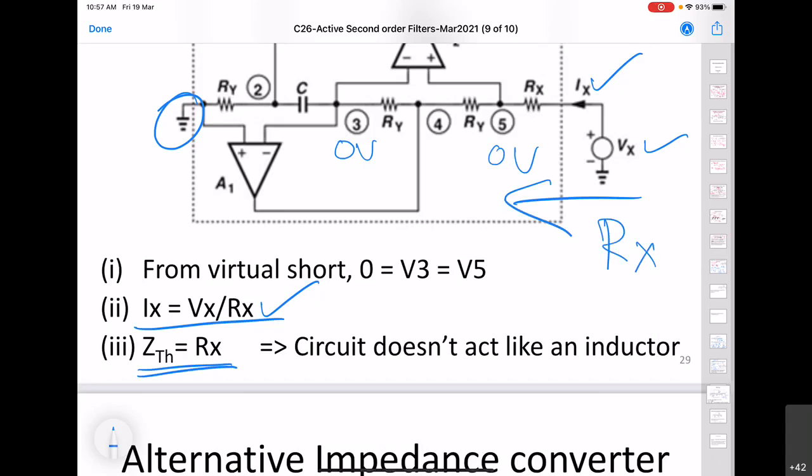It can be used only for a grounded inductor. But anyway, for the low pass circuit, we have already seen that the Sallen-Key circuit is a low pass circuit of second order and active type, which gives certain gain also. So one will always go with the Sallen-Key topology for second order low pass implementation.